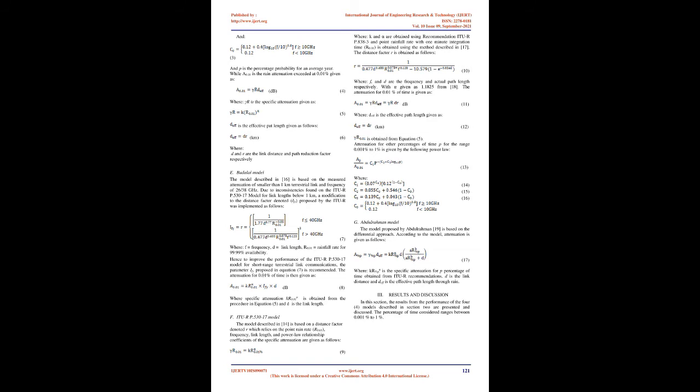need for reduction. The modified ITU-R model is based on measured data from a tropical location. The measured values from the mini-links are used to obtain the coefficients for the new model. The rain rate for 99.99% availability is one of the variables utilized by the modified model. The percentage of time for the range 0.001 to 1 is used to determine the coefficient of the newly modified model. The curve fitting function in the Microsoft Excel suite is used to determine the coefficients of the modified model, while the solver function was used to solve the nonlinear equation of the ITU-R model using the sum of square residuals method to best fit the measured data.